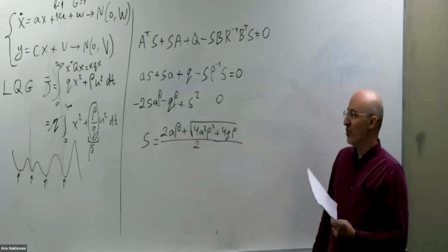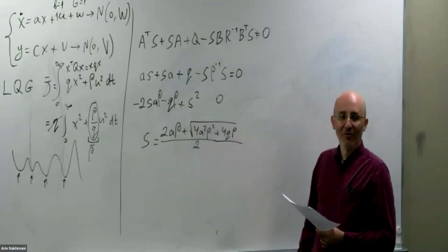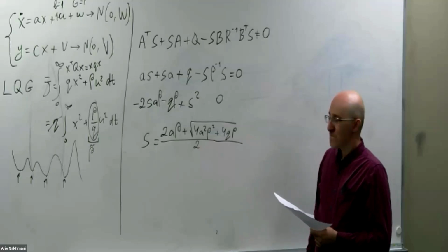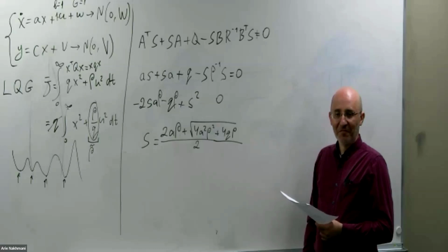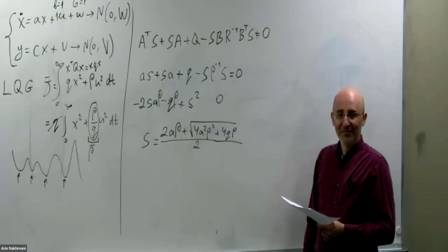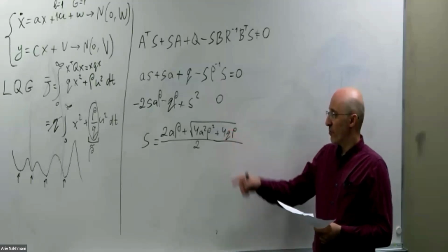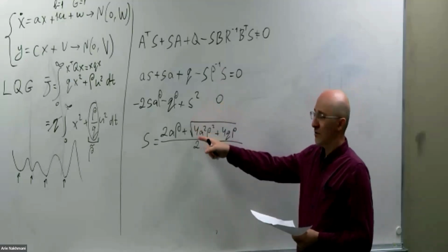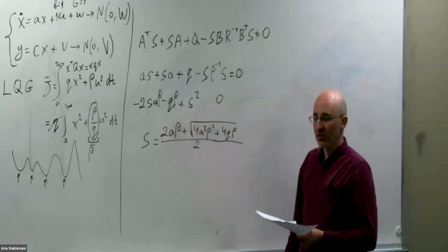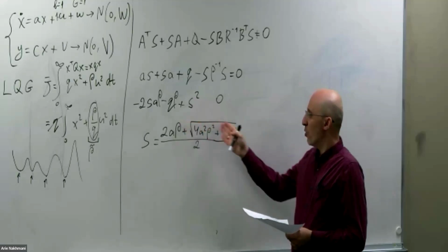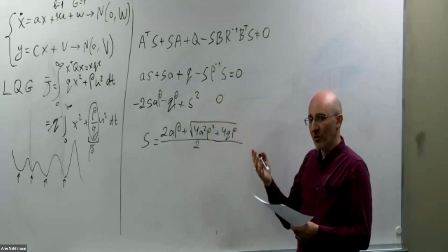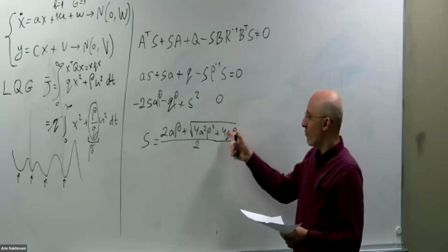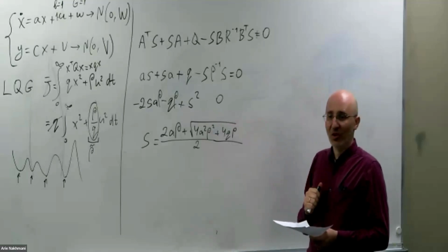Now, could you imagine that minus will also be positive? It will work. In that case, you have a unique solution to LQR. It cannot be, if your system is controllable. It cannot be. And this is clear even from that equation. Again, the absolute value of that part is larger than the absolute value of this part. So if you put minus here, it's definitely something smaller than this one. So subtracting from a smaller value a bigger value, you will get something negative, for sure. No matter what values you pick for all these variables, doesn't matter.